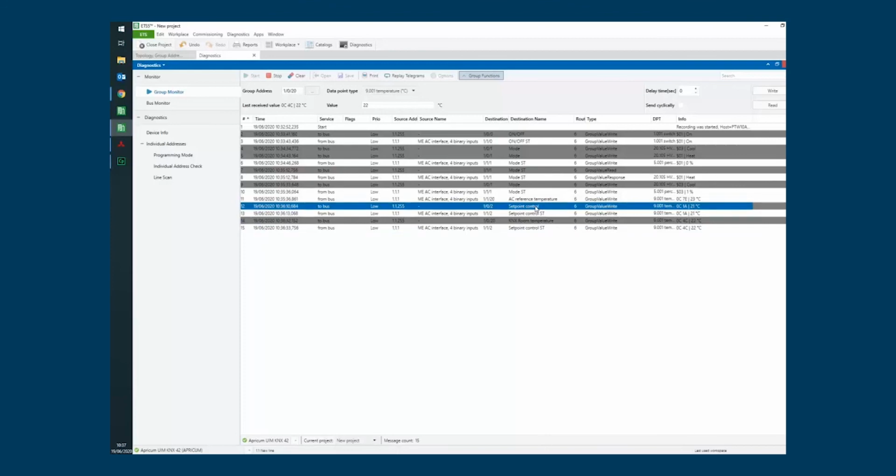Okay, it's 1 degree. So what the interface does is say, okay, you want 1 degree less than the current temperature. So what's the temperature in the return path? It's 23. So I will decrease that degree because the real temperature you want is 22.